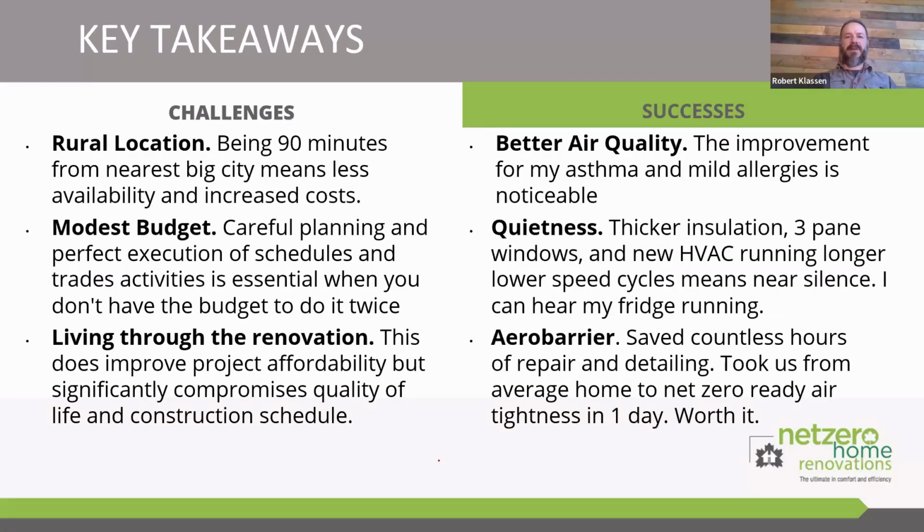One other thing worth mentioning: the frost issues you saw in the picture a few slides back were with the existing windows, which were aluminum frame, double pane, at about minus 25 degrees. Some places in Alberta are regularly colder. In contrast, with the new triple insulated windows, I have not only not had frost, I have not had even condensation, which has been amazing.